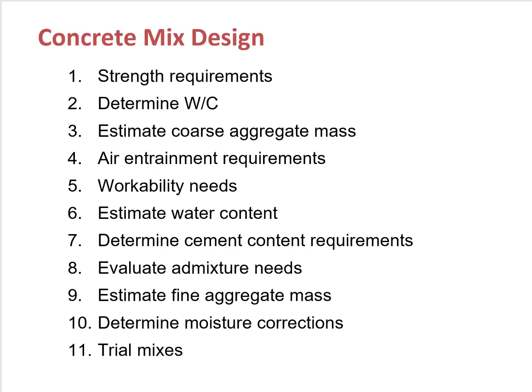The basic steps for concrete mix design include strength requirements, determine water to cement ratio, estimate coarse aggregate mass, and determine whether or not we want to use air entrainment.